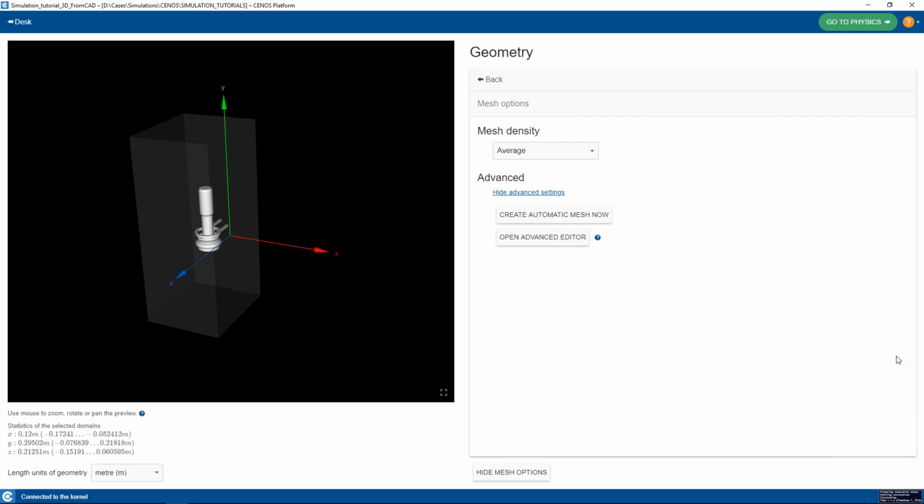So basically, about the optimal mesh, you need to play between two things. The first is the element count, and the second is that you cannot make the mesh so coarse that it would not be appropriate for the specific problem you have.